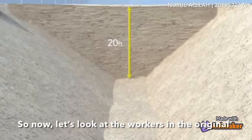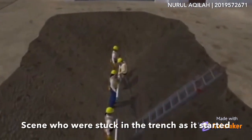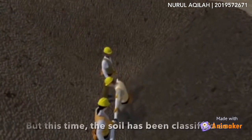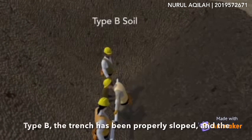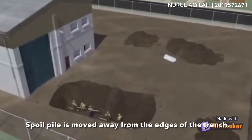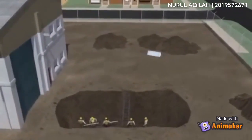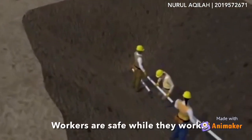So now let's look at the workers in the original scene who were stuck in the trench as it started to cave in. But this time the soil has been classified as Type B. The trench has been properly sloped and the spoil pile is moved away from the edge of the trench. The trench walls are not caving in and the workers are safe while they work.